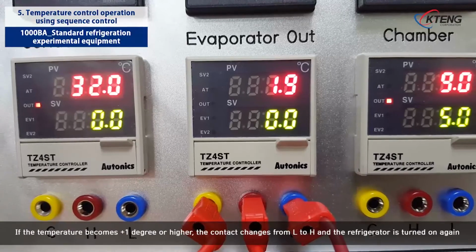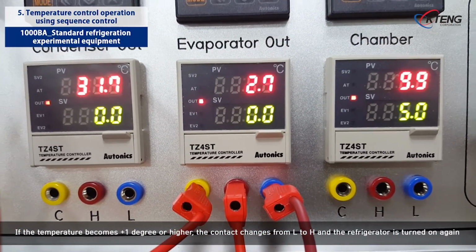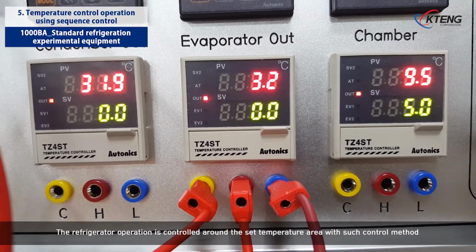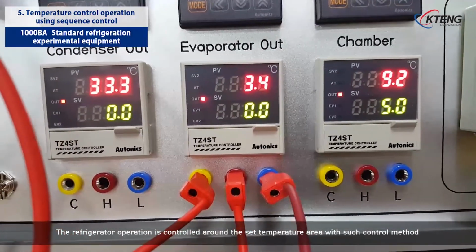If the temperature becomes +1 degree or higher, the contact changes from L to H and the refrigerator is turned on again. The refrigerator operation is controlled around the set temperature area with such a control method.